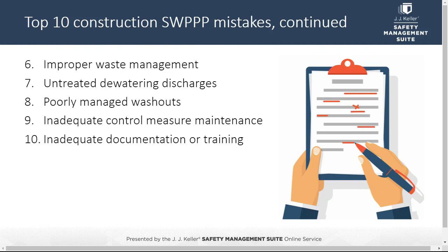Number 7, dewatering discharges from construction sites must be treated in some way. Now this applies to discharges from building footings or other sources. This can be as simple as allowing turbid water time to settle in a holding basin.